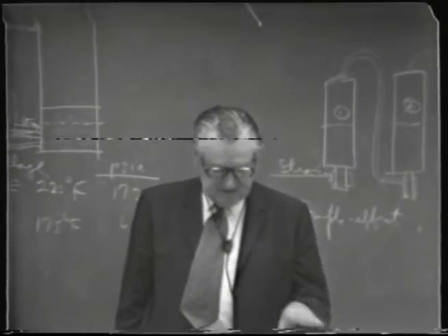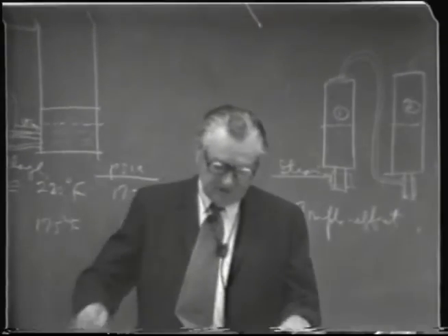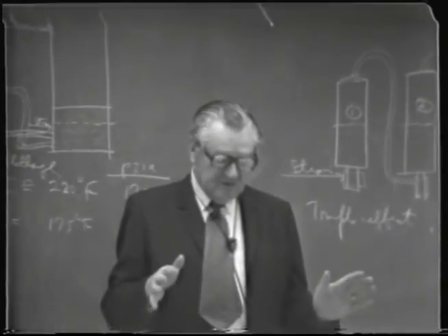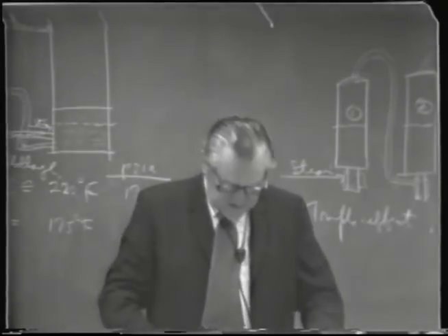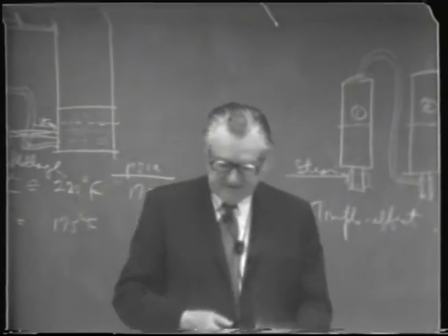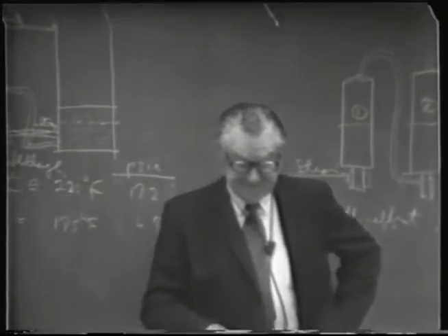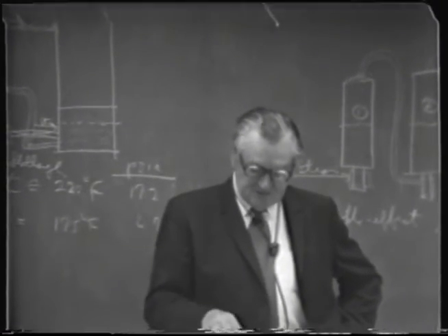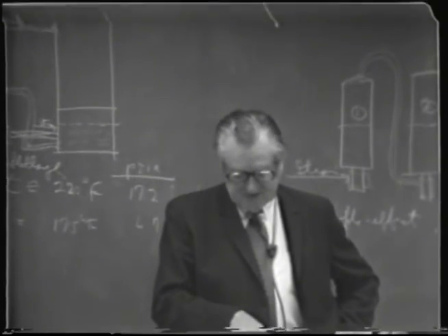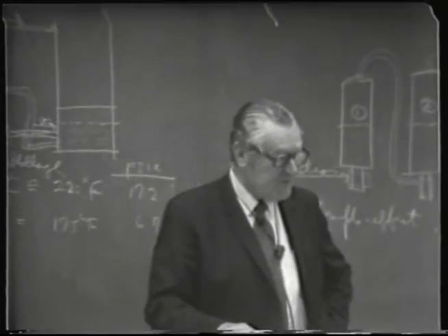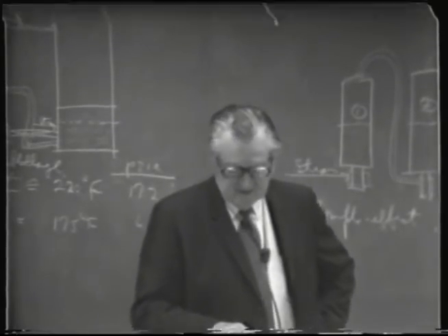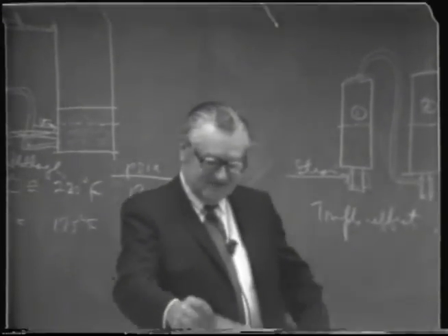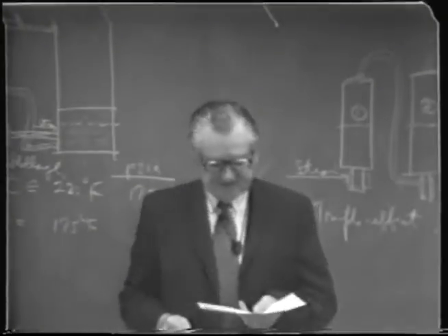I want to mention that these are some of the patterns of distillation columns that are actually in use in the wine industry in California. It's not necessarily for beverage brandy, although some would be, and some would be used only for drawing off wine spirit. But in principle, about the only difference in the two distilling processes would be that in the concentrating section here, the product would be drawn off at the lower point in the column for beverage brandy, and it would be unlikely that there'd be a fusel oil stream drawn off here from the concentrating section.